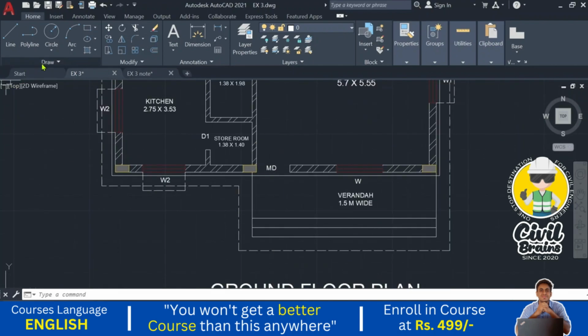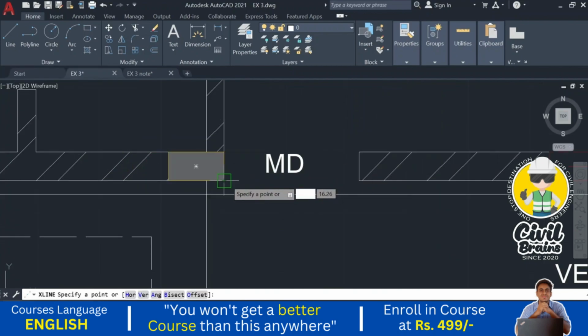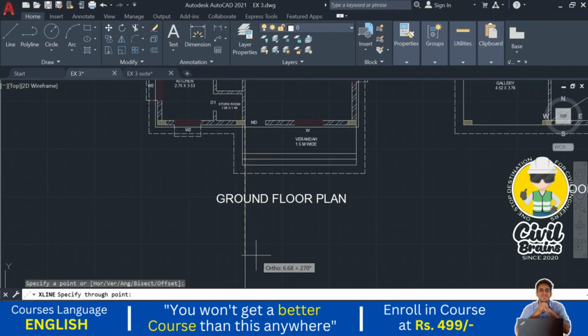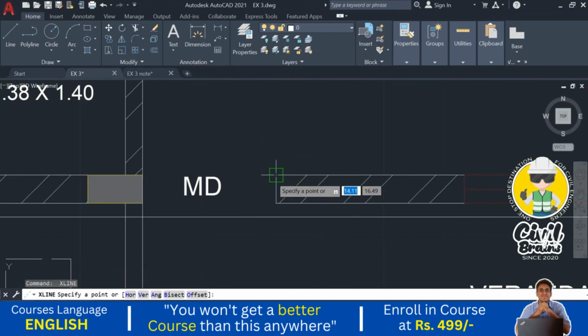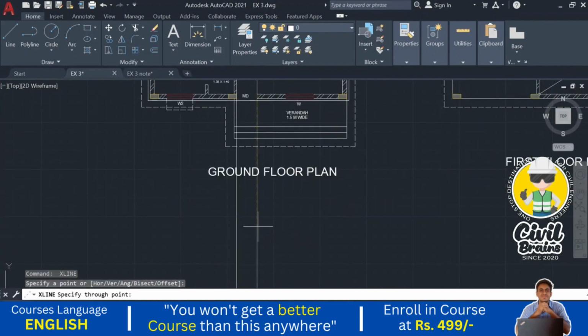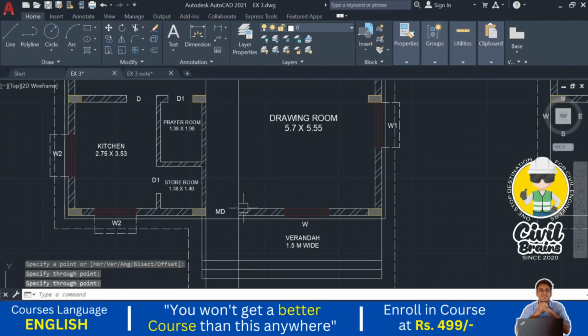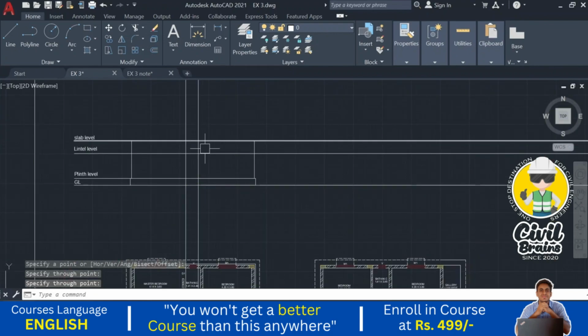I just go to the construction line again, I just click on the construction line. So this is the one end of the door, press enter, and again to repeat that command I just press the space. Again this another end of the door, the two ends of the door I just projected here.